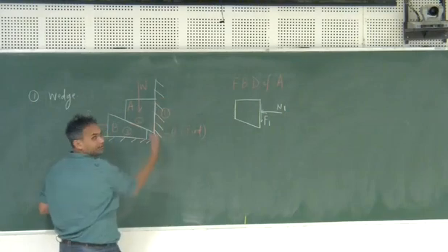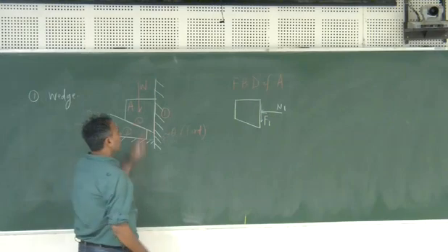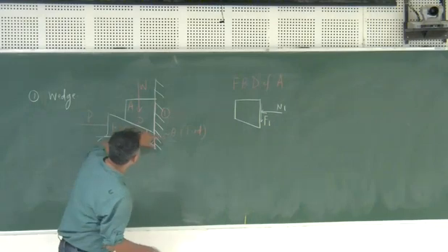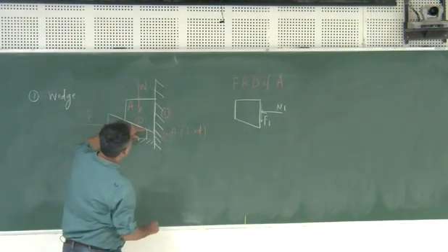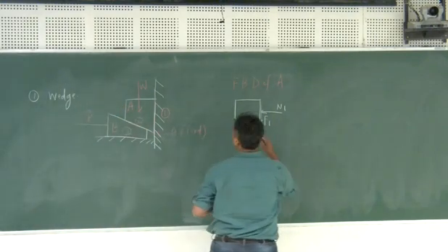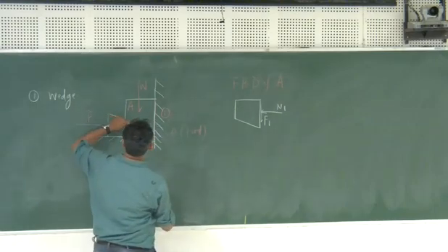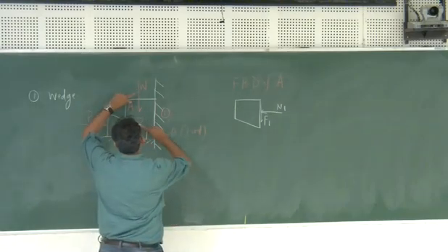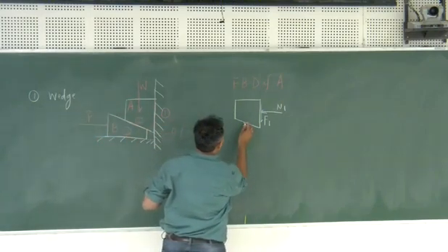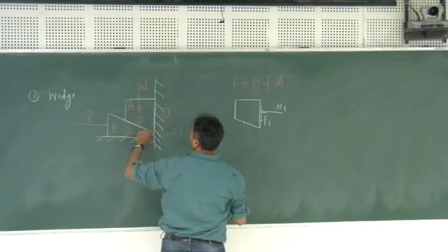Normal from the wall and friction, since it has to go up, so friction is in this direction. To start the upper motion, you have to overcome this load. In a similar way, this block is going inside, so there you will have a load in that direction. Here this is going up, and this has to go inside.